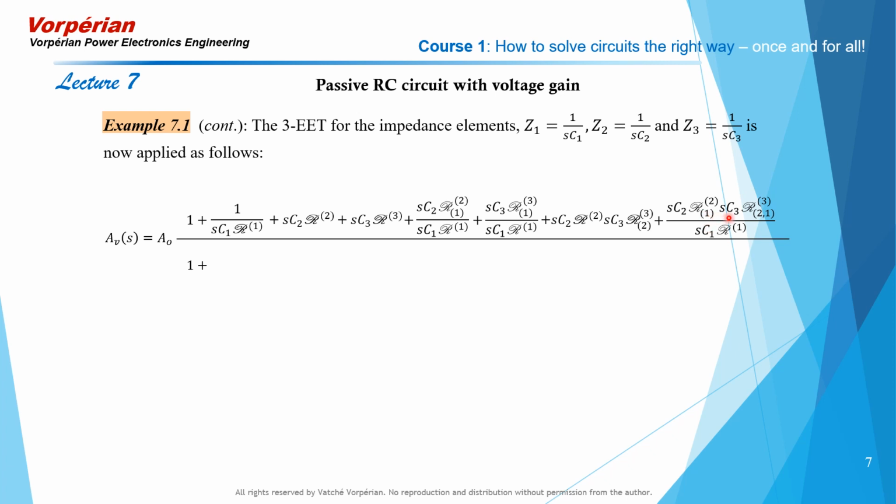Now when we bring in the third element and we pair it with the first and the second elements, the null resistance looking into port 3, the port across which the third element is connected, is computed with ports 1 and 2 in the opposite state of their reference states. And that's the contrast between this, and between this and this here.